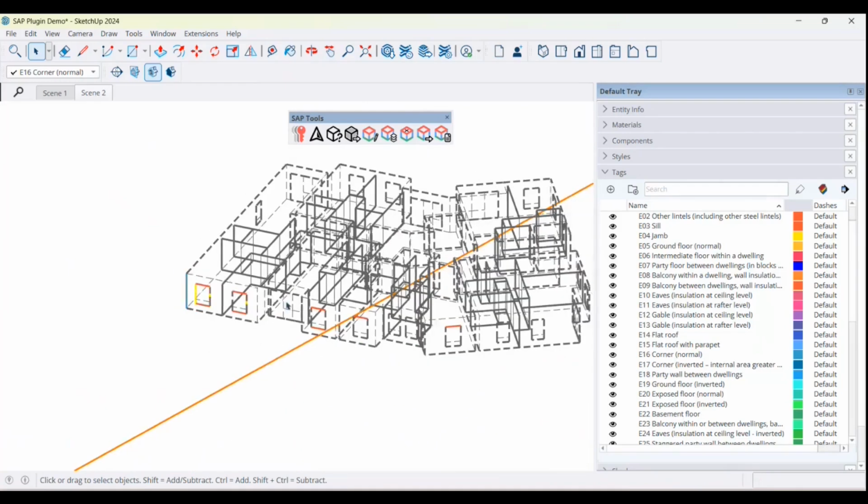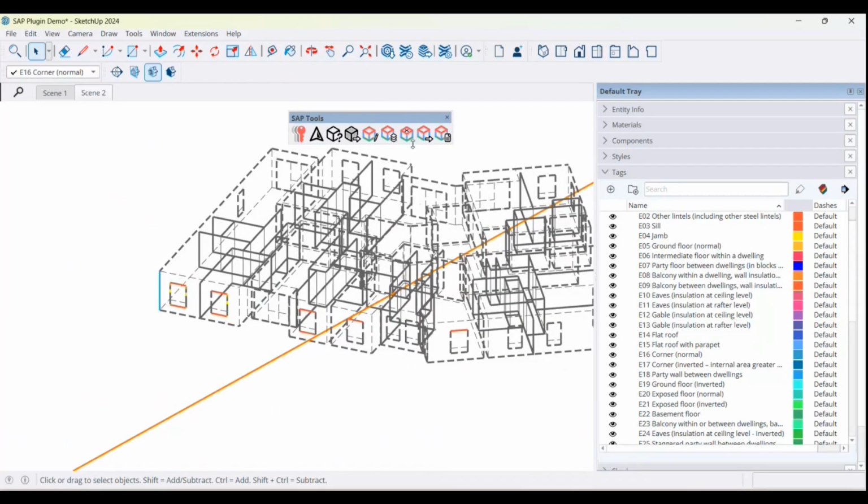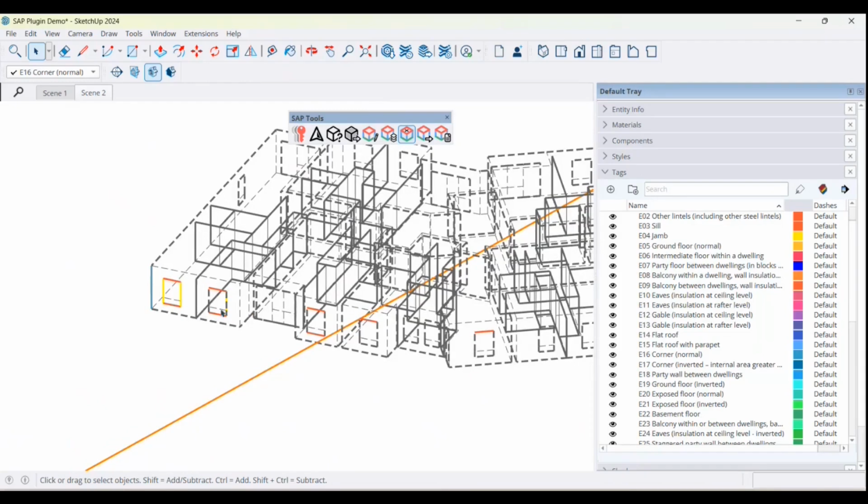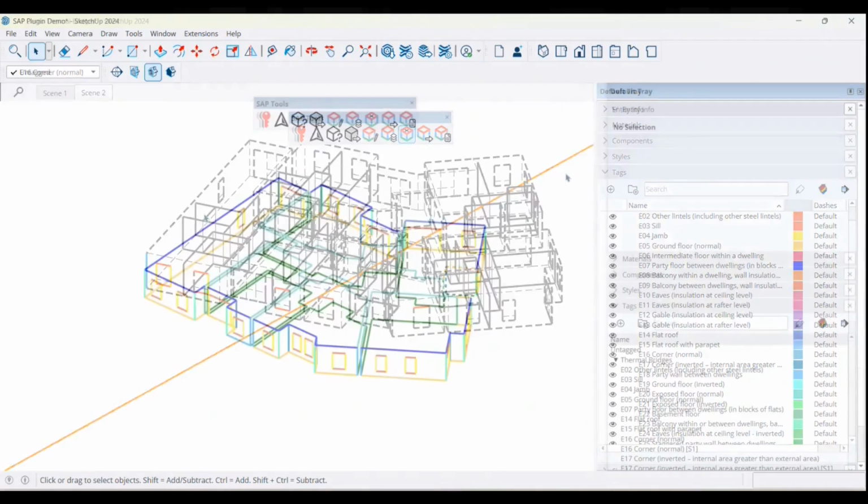Another useful tool when working in this wireframe mode is this button here, which disables face creation. So with that mode activated, when you complete a loop or a face, like drawing all four sides of a window, it essentially stops SketchUp from creating that surface in between, which can become problematic further down the line. So you can simply work with that mode activated.